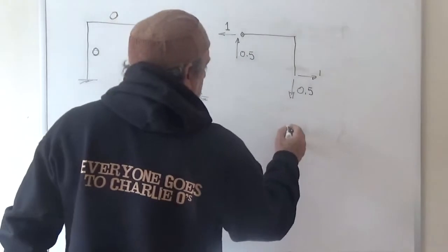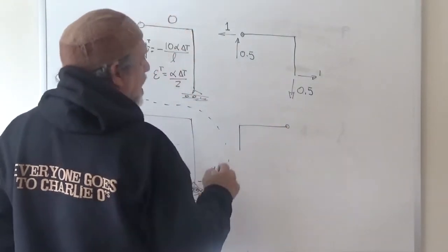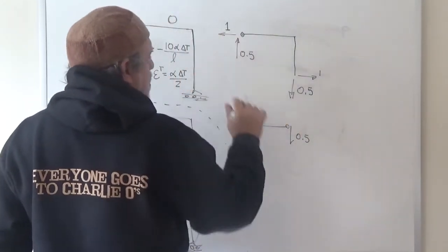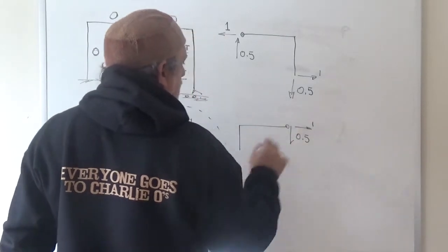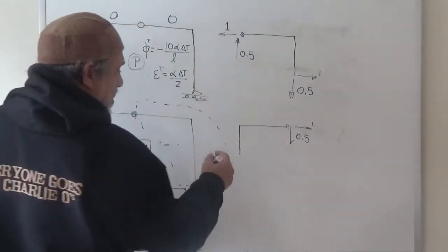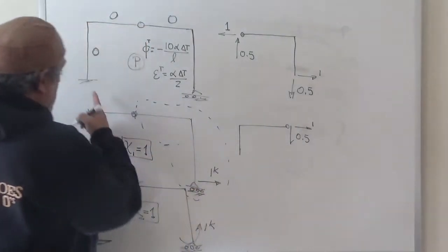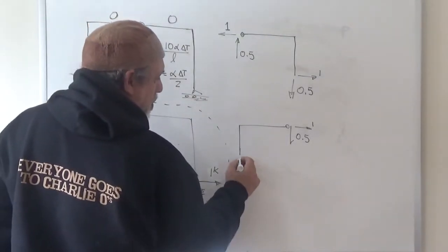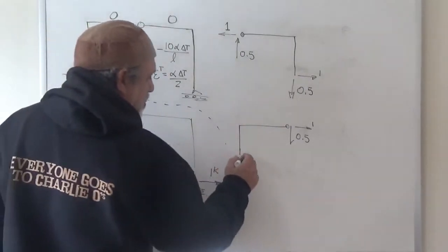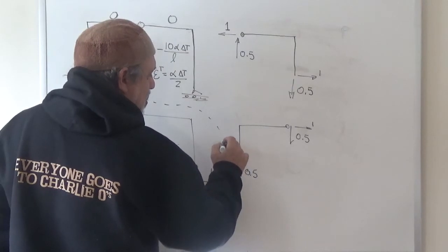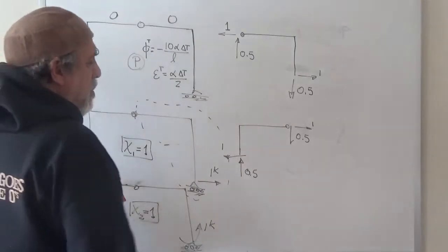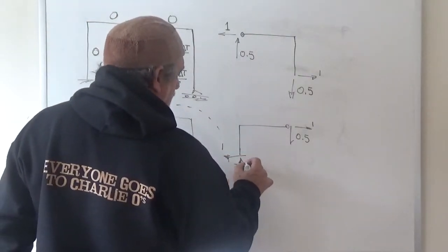It's actually longer from the hinge to the left than down. So this reaction gets transplanted downward as 0.5. This one, which was to the left, gets transplanted to the right as 1. There is no moment there. Here, it's quite obvious. Well, actually, I shouldn't say quite obvious. There's 3 reactions here, right? Because it's a fixed end. So there is a vertical, which from sum of the forces in y is obviously 0.5. There is a horizontal, which from sum of the forces in the x direction equal to 0 is obviously 1. And then summing moments about this point, and let me write that equation.